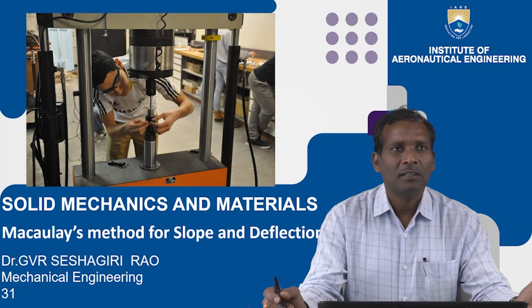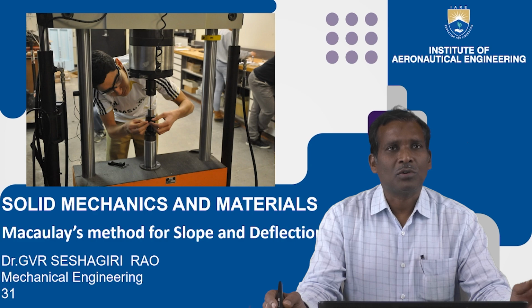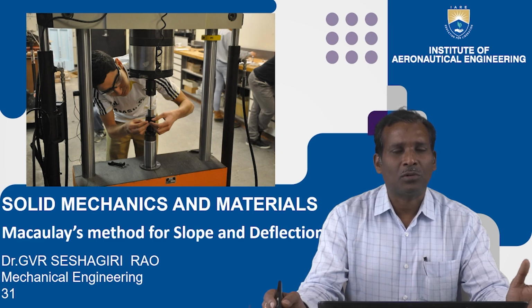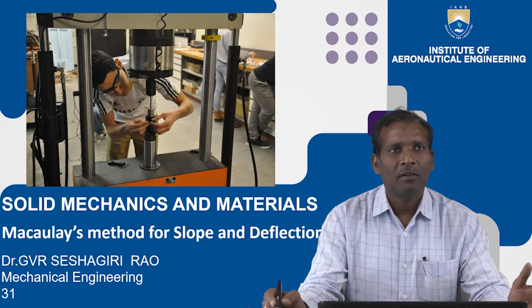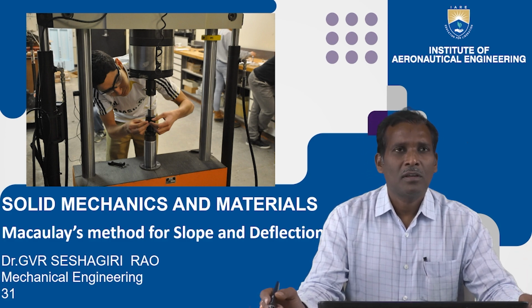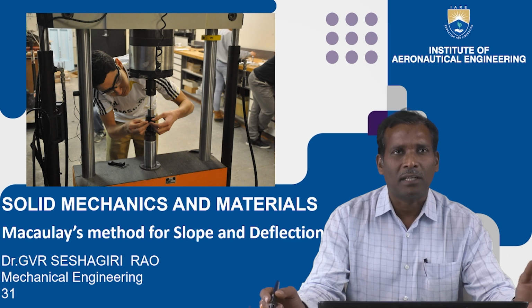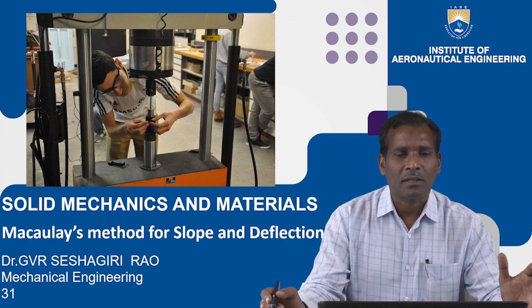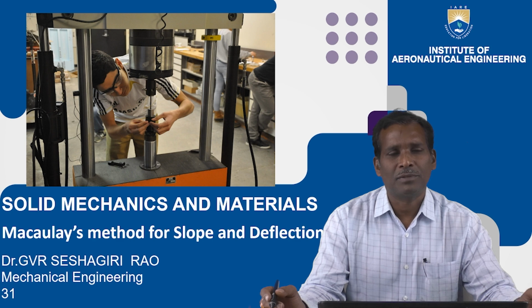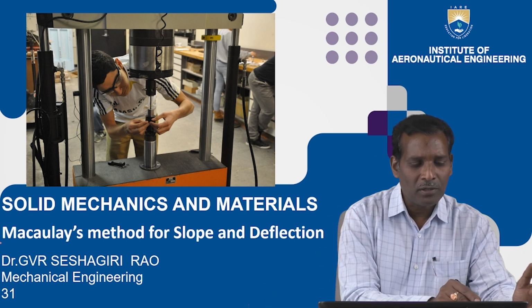We are discussing solid mechanics and materials. In the previous session, we discussed slope and deflection of various beams: how to calculate the slope and deflection of a beam when it is subjected to a single load or various loads. In this topic we have discussed the methods. How many methods are there for calculating the slope and deflection of beams? We already discussed the double integration method, and in today's session, Macaulay's method